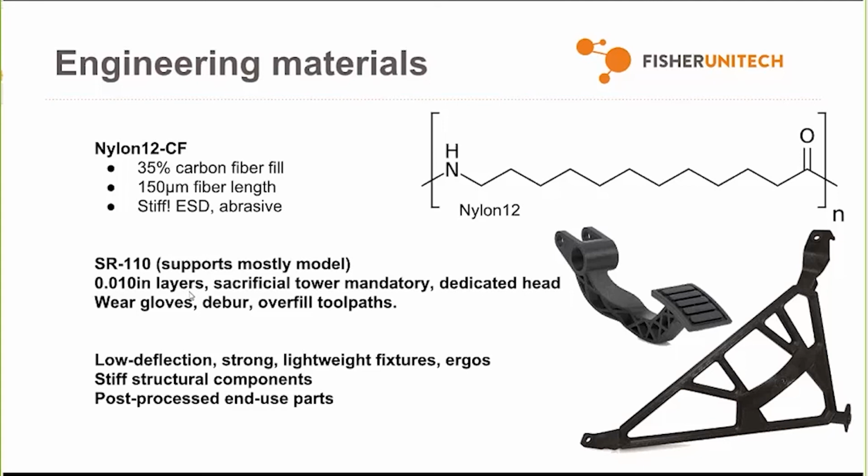If you are processing your parts in Insight rather than GrabCAD Print, I would suggest adding a slight negative spacing between contours and rasters. Now, your results may vary when you actually print, but I've found that sometimes we get a little bit of under extrusion, especially on the bottom-facing layers. And that's especially likely to happen if your tips have a lot of hours on them. This stuff eats through tips.